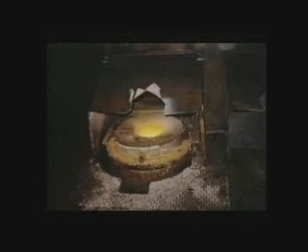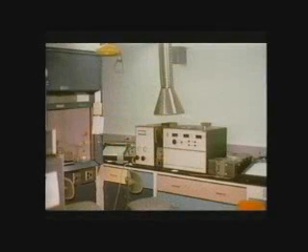This receiving hood over an induction furnace was cut by employees because they could not see inside to check the melt. Adding a flange to a hood will normally increase its effectiveness by reducing airflow from areas behind the hood where no contaminant exists, and improving velocity distribution in front of the hood where contaminants are generated. Flanging can reduce airflow requirements by as much as 50%, resulting in lower capital and operating costs for the system.